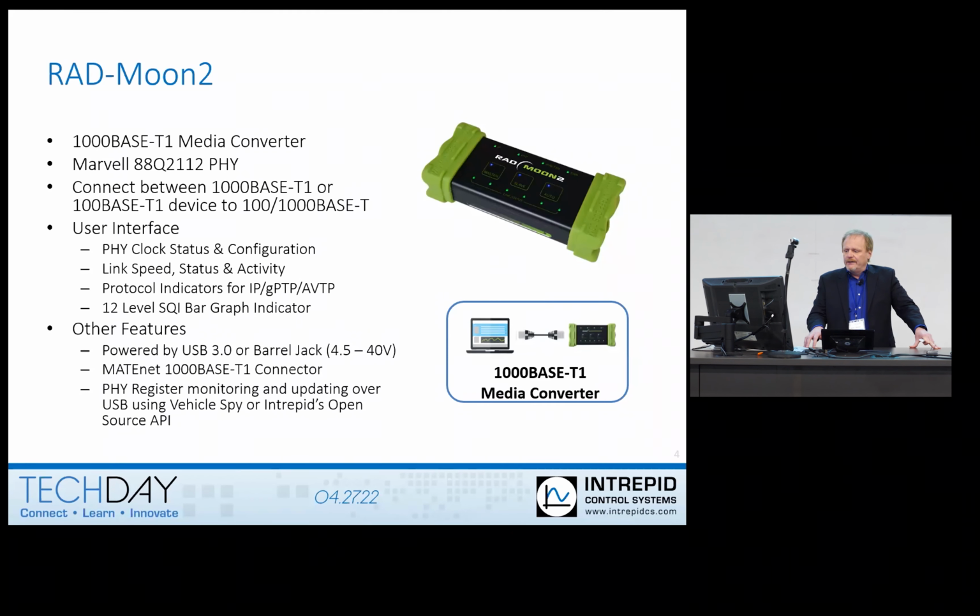We use the MACnet 1000BASE connector for 1000BASE-T1. There's also Rosenberger, which is frequently used by some of our customers. And we're working on a translator board that has MACnet to the Rosenberger HMTD for those customers that need that.